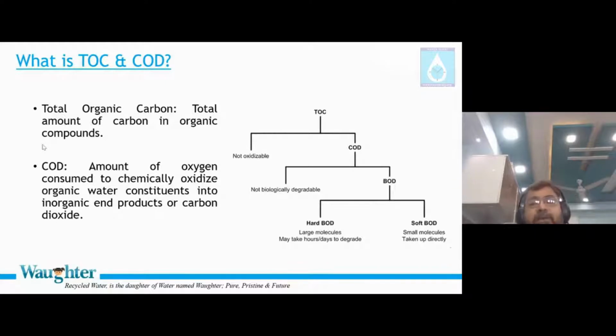Okay, but COD minus NBCOD is not BOD. So by this formula, you should not understand that COD minus NBCOD is equal to BOD. No, BOD is just an experimental number. The right term, I should write on this slide, is BCOD, not BOD. Thank you very much, Twinkle. So next time we'll improve this slide. We should write BCOD here, not BOD.